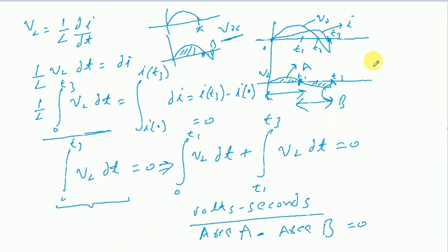And if you want to evaluate the average values, previously we used to have that function in which the total time period still remains 2 pi, but previously we used to have the limits from 0 to pi. But now we can see that the voltage keeps on conducting, so in the case of an RL type of load, we will have this value equal to beta. Beta in practice depends on the value of the inductance and for how long the current keeps on conducting. So this can vary from circuit to circuit or application to application.